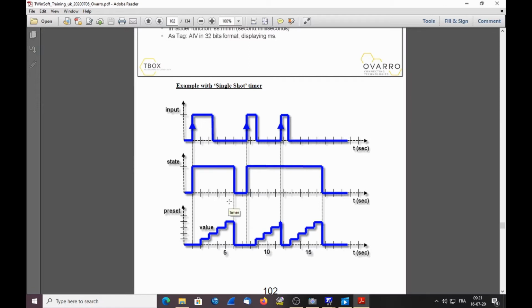I would like that when I am in maintenance status, a lamp is on to inform the site that we are in a maintenance status. So this digital tag will activate the lamp. As long as I am in maintenance, the lamp will be on. When the timer starts, I will deactivate some features, and when the timer stops, I will reactivate the features.